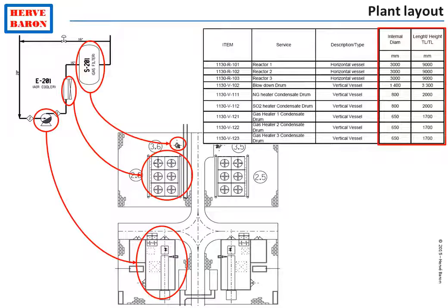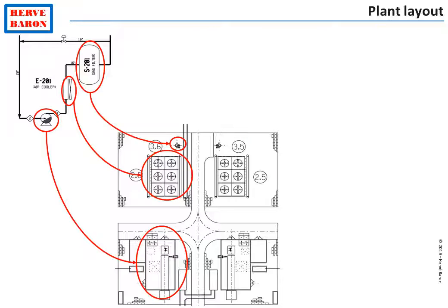Rotating equipment, heat exchangers, and other types of equipment are not sized by process. Therefore, inquiries to vendors are necessary to obtain dimensions. In the case shown here, for instance, that includes a gas compressor and an air-cooled heat exchanger, inquiries will have to be made to vendors of these two equipment, the gas compressor and the air-cooled heat exchangers, to get dimensions in order for plant layout to be able to produce the unit plot plan.